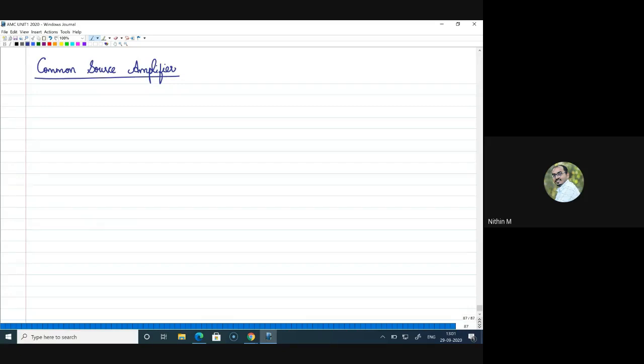So I'll just take this as my first case. So this is case 1, right? So what I will do is I'll take a common source amplifier. So I understand what is meant by common source. That means the source terminal should be made common to both input and output. Now, how will I apply input? Input can be applied to the gate. So a DC should be there, and on DC I have to apply a small signal. So this I call it as VGS, and this I call it as small vgs, right?